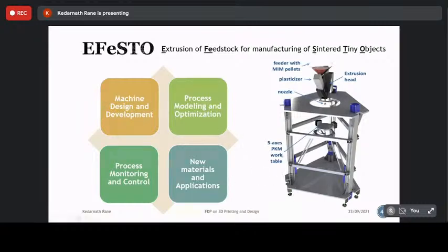A parallel kinematic table was developed using this kind of system. We made the unit. We used a commercial extruder and made it stationary, because we can easily feed. There is no need to move this bulky system, because it's very bulky, almost more than 20 kilograms in weight. So we wanted it to be stationary, and everything else is moving. The bed is moving here, and the productivity is very high. You can rotate so that you can control the requirement of support structures, and there are many other merits of these systems.